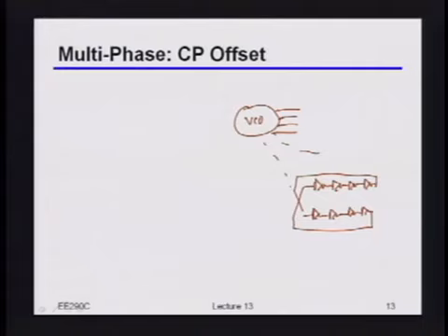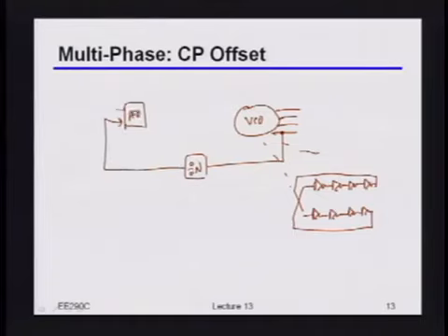So if I can just make it so that I just shift basically whichever phase it is that I use to take the feedback off of. Right, so let's say that's my PFD. That's my reference clock. And I'll just draw my loop filter here. Actually, I'll really draw it this time. So now I'll actually draw the charge pump just because you'll see in 1 second I'm going to be mucking around with that a little bit. Okay, so that's my charge pump, of course, my loop filter.